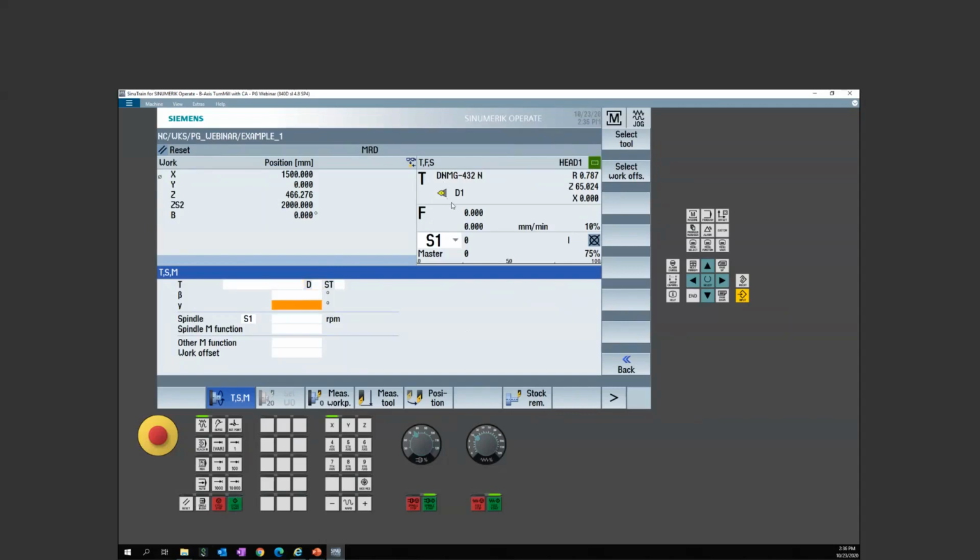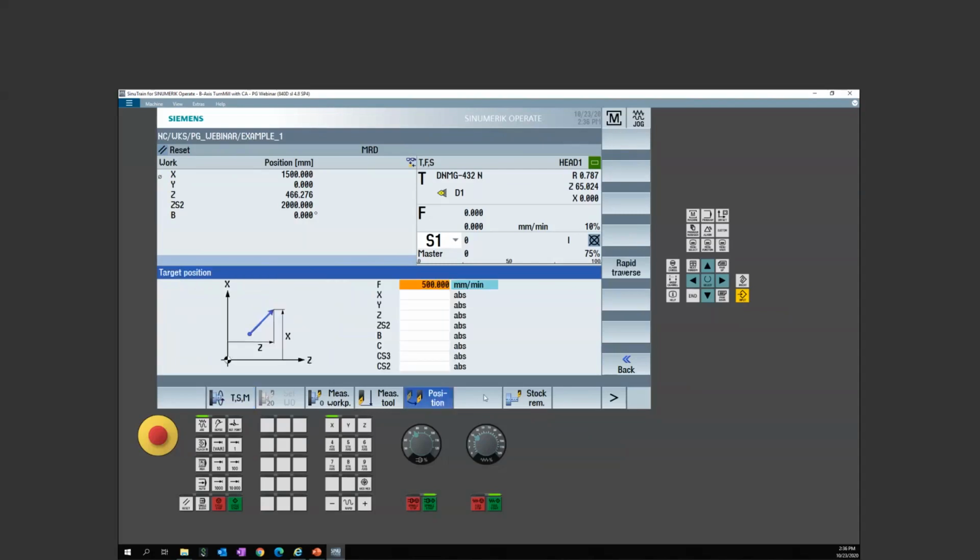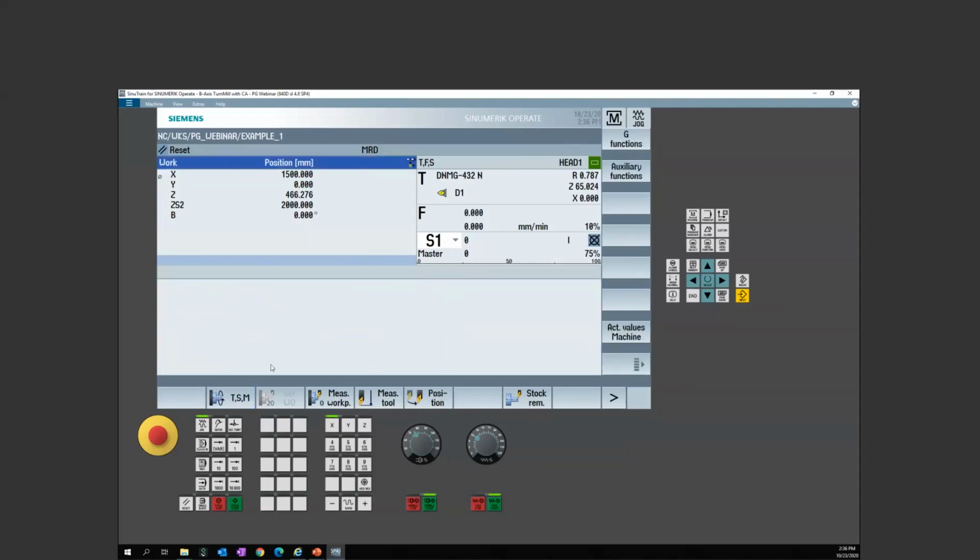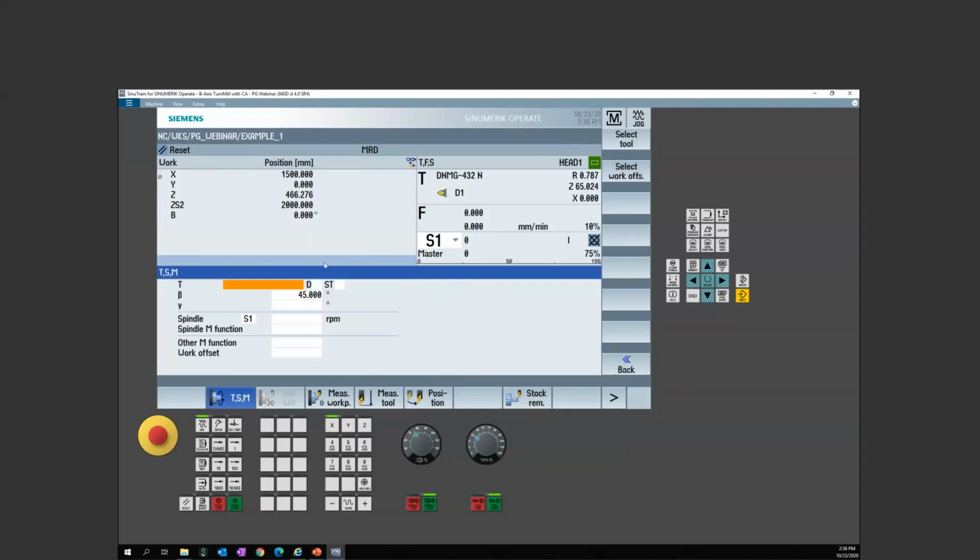So now watch the tool definition, the tool description. Let's say I position the B axis through the beta. I'm not doing it as a direct move because then I won't get compensation. All right, so I'm going to do beta here, and I'm swinging to 45. Look, it just changed the tool orientation. So no longer is it centering the insert on the center line of X. It's now, if I position to 0, going to be at 2 tangent points. And if I swing this all the way to 90 degrees, watch, it changes the orientation again.